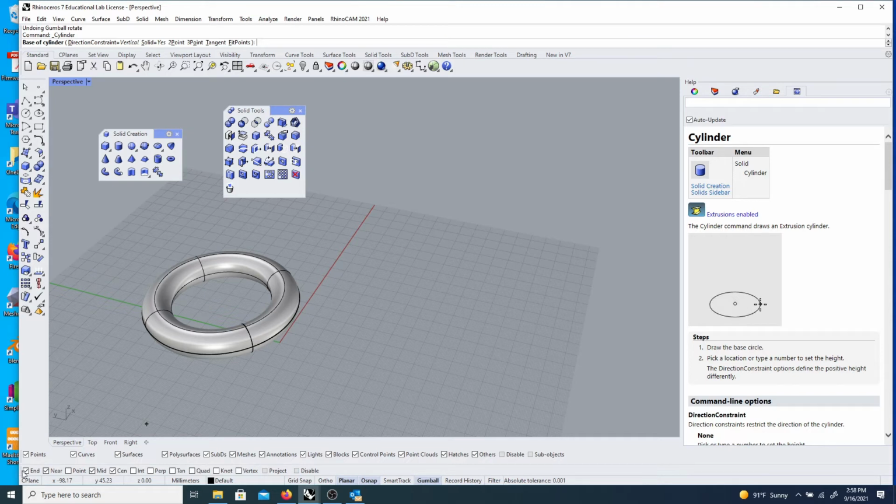You've got all these little checkboxes for particular geometric points on your solid objects: end, point, mid, center, intersection, tangent, quadrant. So this is just bringing it back to basic geometry. And it'll alert you when you've snapped to something. So I want to snap to the center of this thing. I get close to the outside diameter of it.